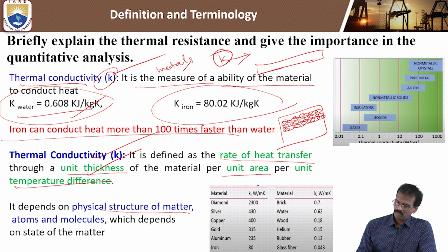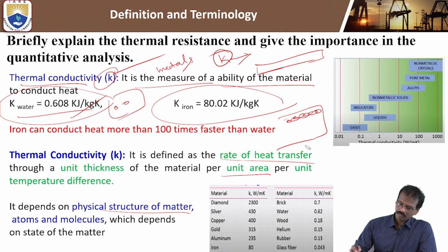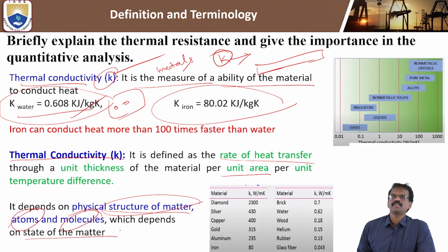But in case of fluids, the distance between the molecules is very high. There is no such vibration between them, and they don't have free electrons to carry the heat transfer. So this is the phenomenon. Thermal conductivity depends upon the physical structure of the material and the atoms and molecules, which depends on the state of matter.